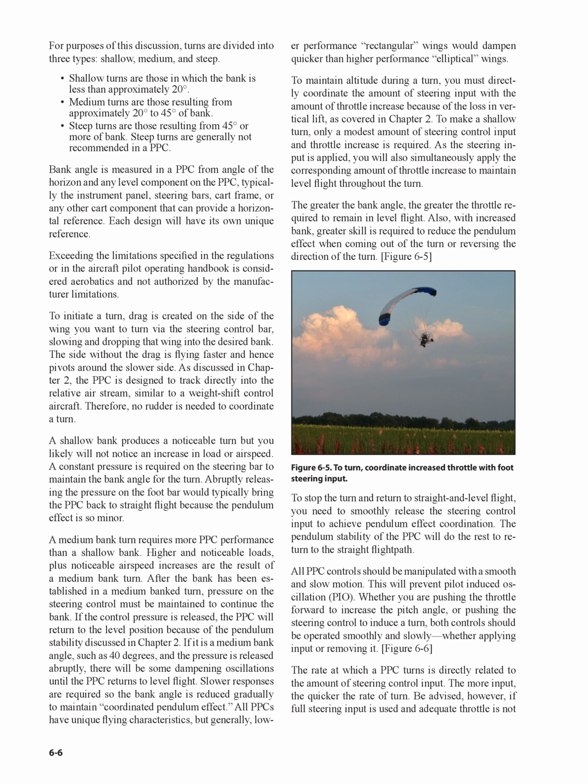Higher and noticeable loads, plus noticeable airspeed increases are the result of a medium bank turn. After the bank has been established in a medium bank turn, pressure on the steering control must be maintained to continue the bank. If the control pressure is released, the PPC will return to the level position because of the pendulum stability discussed in Chapter 2. If it is a medium bank angle, such as 40 degrees, and the pressure is released abruptly, there will be some dampening oscillations until the PPC returns to level flight.